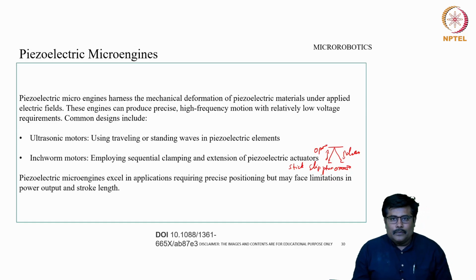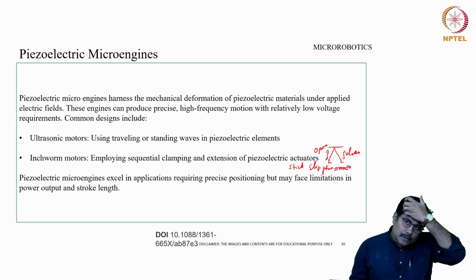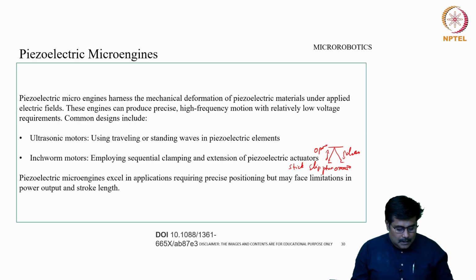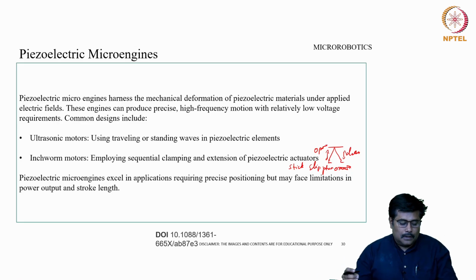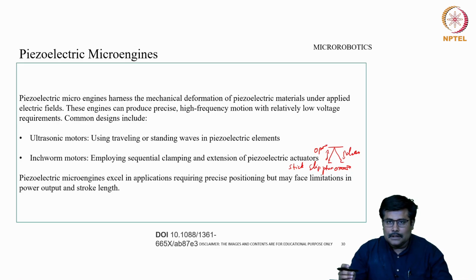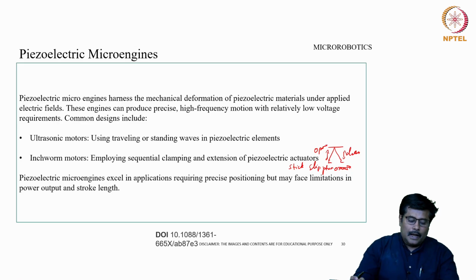Now, in today's lecture, we will discuss more on this ultrasonic motor. The piezoelectric ultrasonic motor uses an ultrasonic frequency with piezoelectric vibration generated waves, and these waves transform electrical energy into a rotary or translating motion. The USM receives more attention because it offers distinct qualities over traditional magnetic coil based motors, such as miniaturization and greater accuracy.